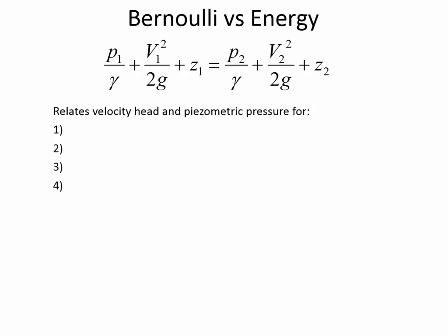Because fluids that do have viscosity are going to experience energy loss because they will be delayed at the edge of the pipe, and at the center of the pipe they'll be flowing more freely. But this mystical inviscid fluid would be able to just flow through a pipe without any shear stress resistance whatsoever. So, right. The first assumption is inviscid. What's the other?